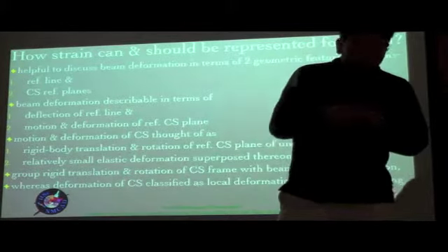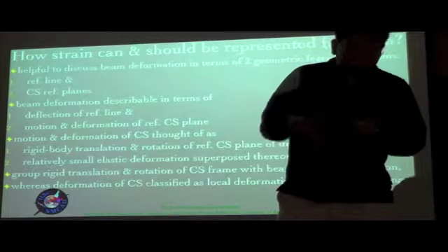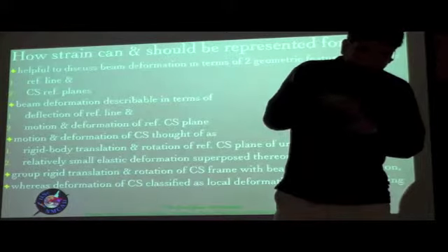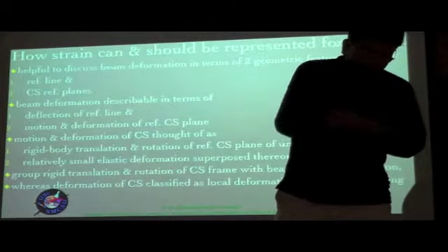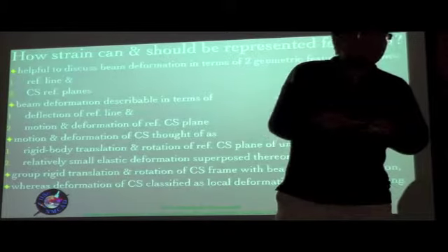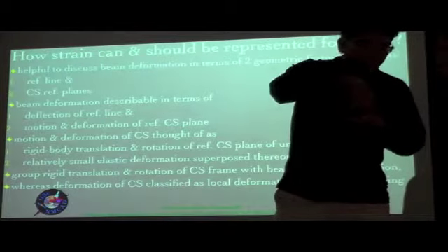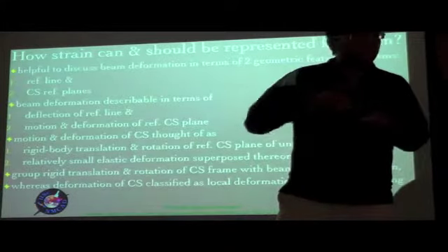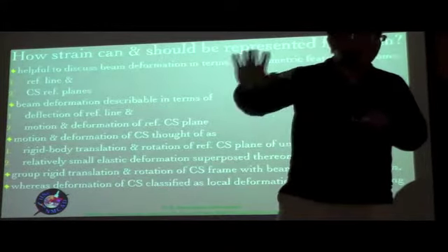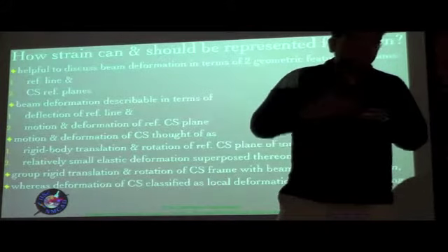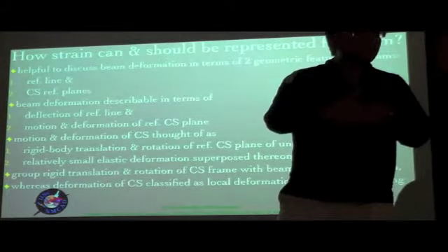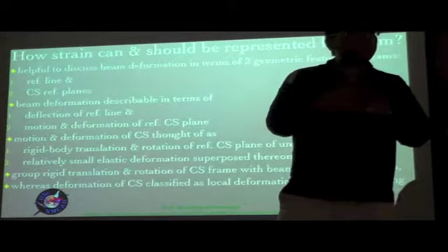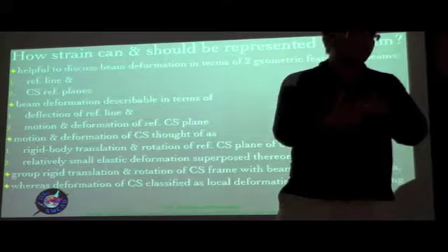Okay, so now if we take this rectangular cross section, now if you take at some location a line element which is perpendicular to the plane, if you're thinking of this as a plate, let us say. Okay, so there's a line element over here. Now warping is such that it is a function of x1, x2 and x3 apart from time. Okay, all three spatial coordinates. Now we have already fixed the cross section, so which means x1 is fixed. So at that cross section it is a function of x2 and x3, right?